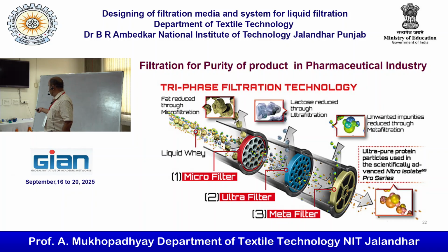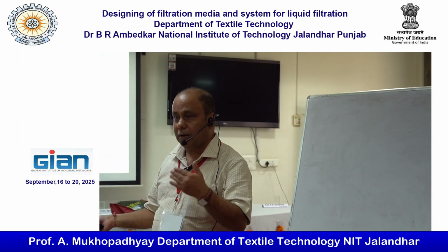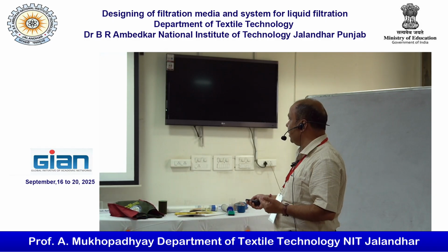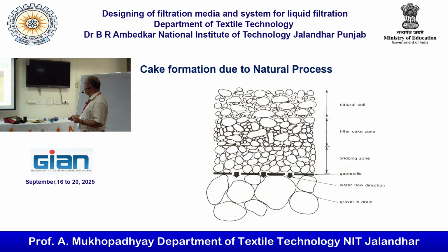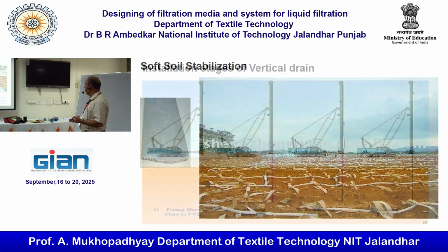Now this is the geotextile application. I have shown you one of the pictures, and this is a similar picture. There also the role of filtration is very important. Now if you see the natural cake formation, it might take 10 years for geotextile, but in the case of liquid filtration, within seconds the cake will form. That is the difference. Here also it is a kind of filtration that happens in the case of geotextile, but whenever we talk about liquid filtration, cake formation will be very rapid, quick. Within seconds the cake formation will take place.